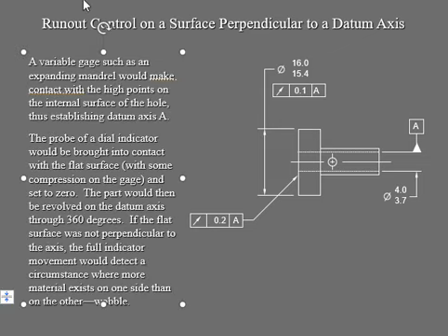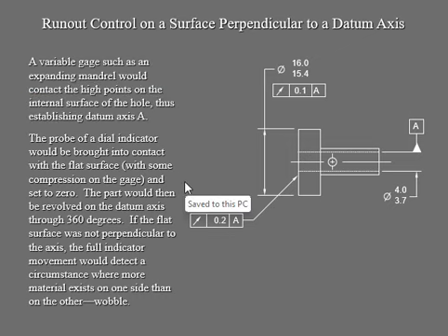Then when you probe it, probing means we're using an instrument, in this case your dial indicator. So when you probe it with your dial indicator, meaning checking the verification and verifying that you brought it into contact with your flat surface, we're going to set it to 0 to start, and then that part is going to revolve, right?